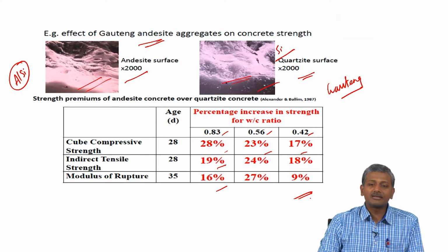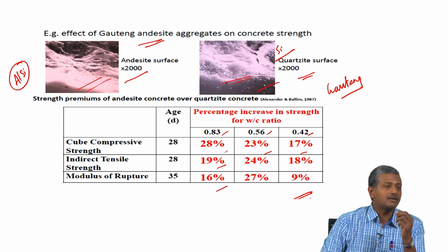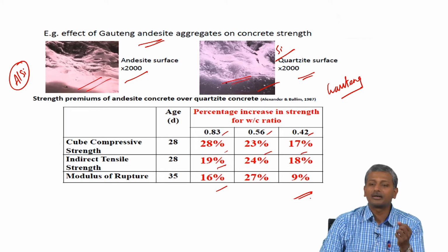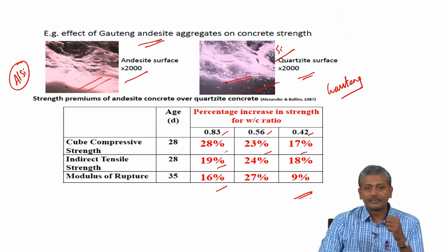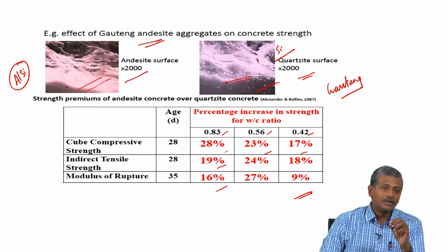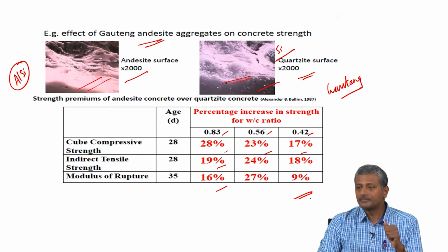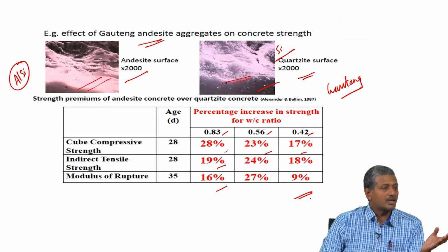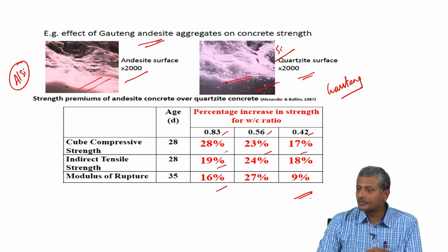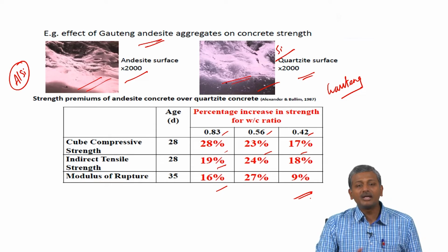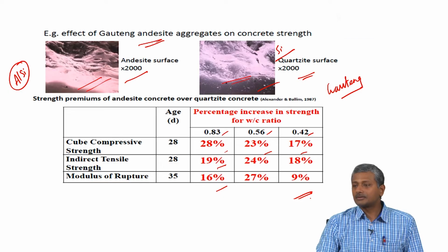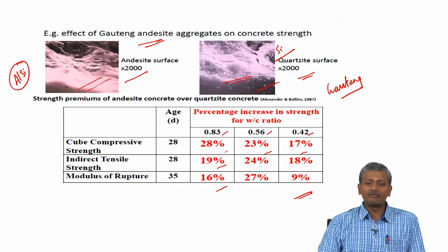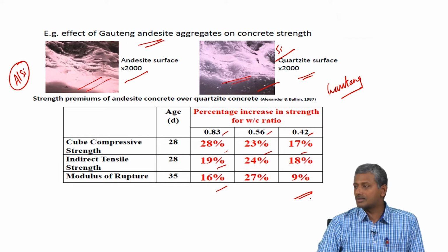The problem with that is basalt, when it crushes, basalt is extremely fine grained crystals. When it crushes, it forms very fine particles. So as a result you get aggregate that can absorb a lot of moisture, whereas granitic aggregates, when you crush them, do not make too many fines, excess fines are not there. So the kind of effects you get of crushing the rock into fine aggregate are very different depending on the type of rock that you actually start with. So there are distinct benefits to using one type of aggregate or another, but you are obviously constrained by what you have available locally. You can't transport aggregates over large distances.